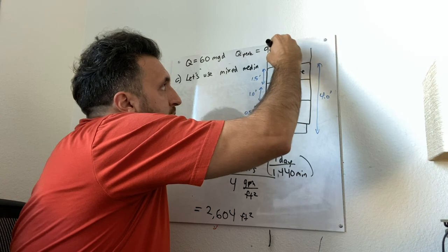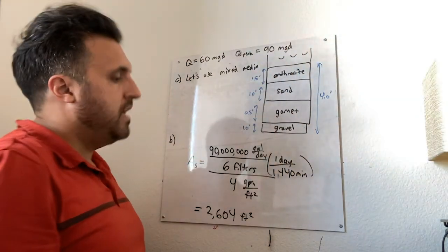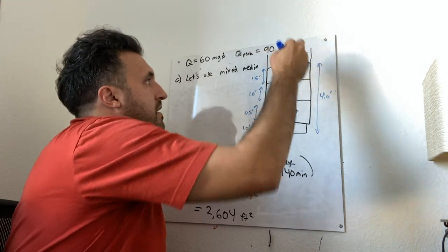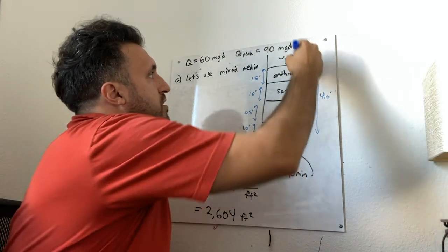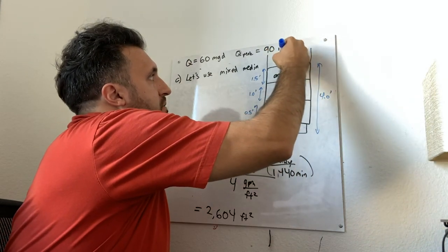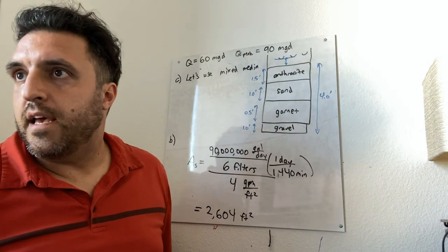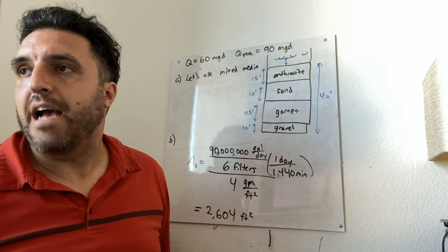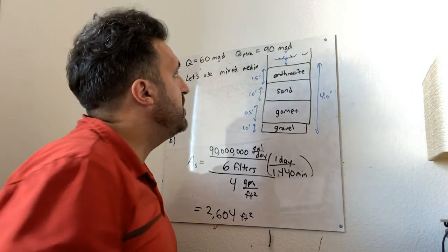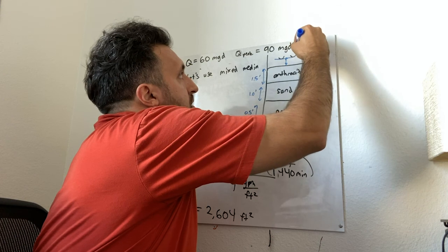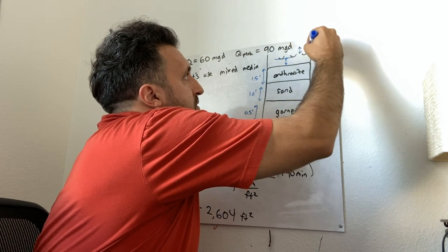So our troughs are up here, delivering the water and collecting backwash. That distance from the bottom of the trough to the top of the media should be a maximum of 30 inches. Let's use 2 feet. The freeboard should be 1.5 feet to 2 feet, so we'll use 2 feet. So this is 2 feet. This is 2 feet.